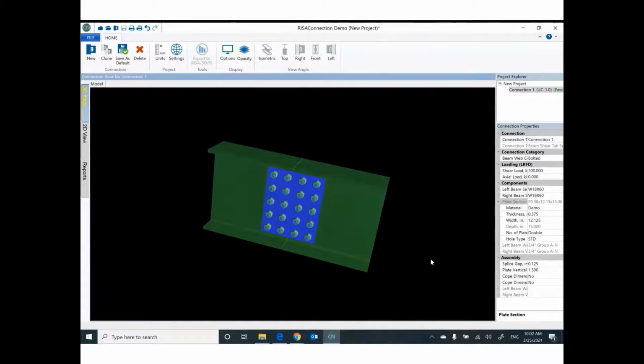So it looks like a game. Do you know there is a game, Meccano, for kids? You are building a few things, and the final shape you can check. So we are right now trying to build our connection and put in your axial force, shear force and the axial force from structural analysis. One of you will say, hey, where is the moment? We don't have moment, because at the first step you chose a shear connection. So we don't have moment.